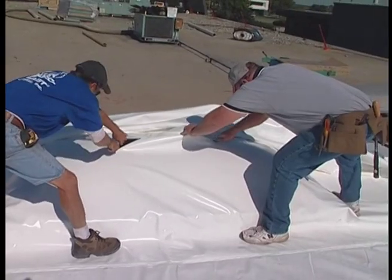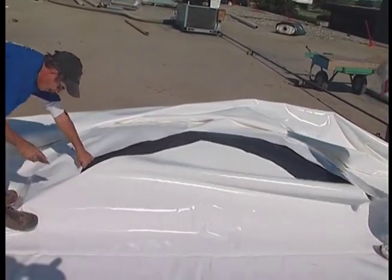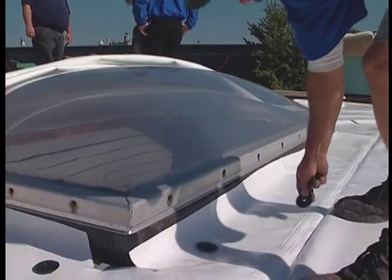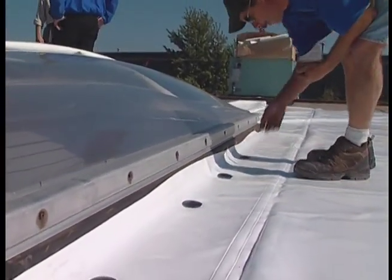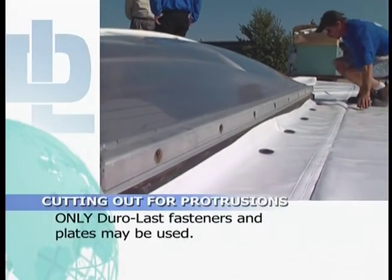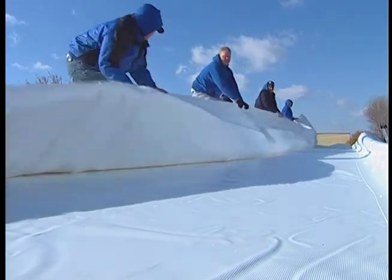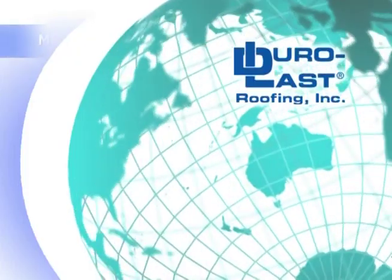Note that when the roof membrane has been cut and installed to fit around the protrusion, the fastening pattern for the protrusion's perimeter will be the same as the deck membrane, or a maximum of 18 inches on center and a minimum of 1 fastener around the perimeter of each protrusion. Only Duro-Last fasteners and plates are approved and accepted. You now have the knowledge you need to proficiently install Duro-Last roof deck sheets.